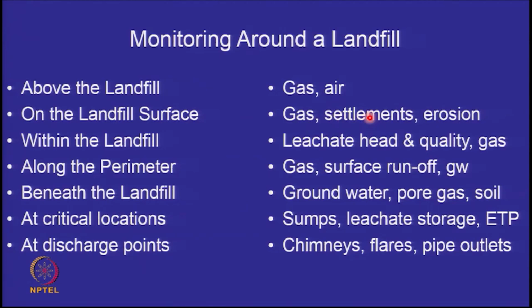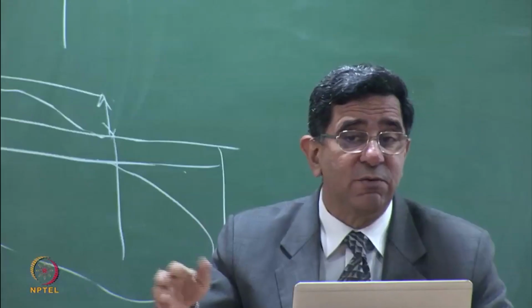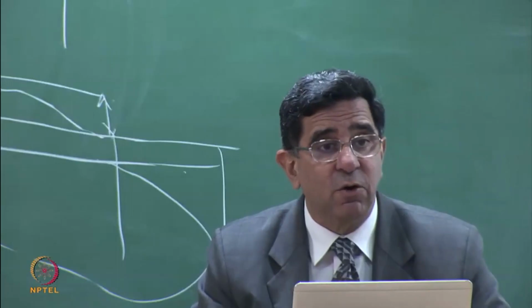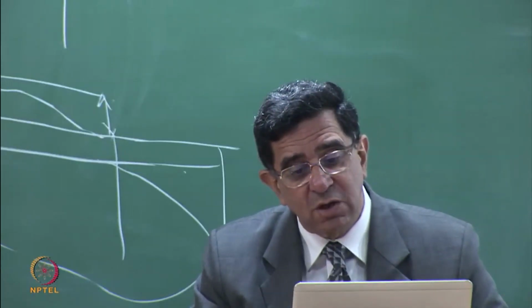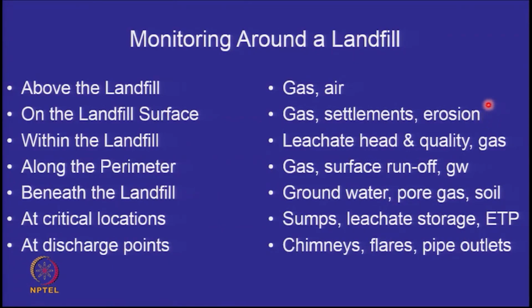You are interested in how much the landfill is settling, so you need to monitor settlements of the landfill. And this is important because landfills can settle by 10 to 15% of the height depending on the amount of organic content they have. And you also want to know about erosion. Are erosion gullies forming on the landfill surface? So you would like to monitor erosion.